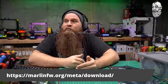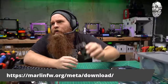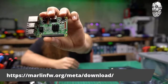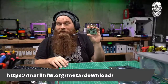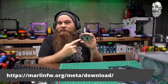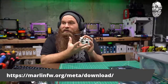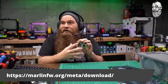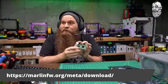Klipper is its own firmware, but all its kinematics and such are run off a Raspberry Pi, which is much more powerful. This is a 64-bit processor with multi-core and a real MCU and all that stuff. So this is what's running your kinematics. You put OctoPrint on here, you put Klipper on here, you put Klipper firmware on your printer, and this controls all of that.